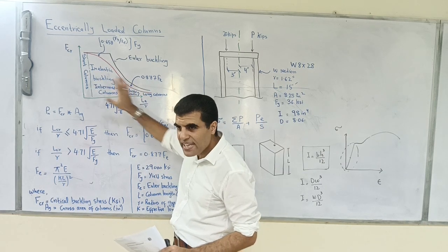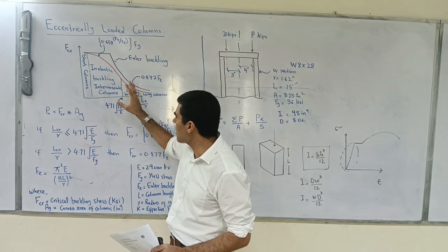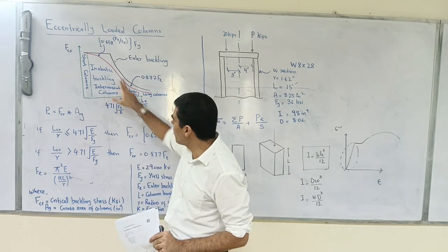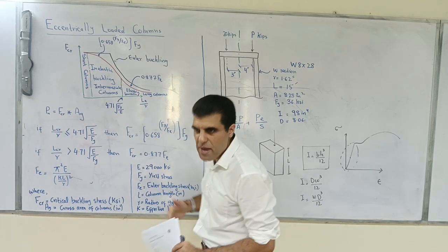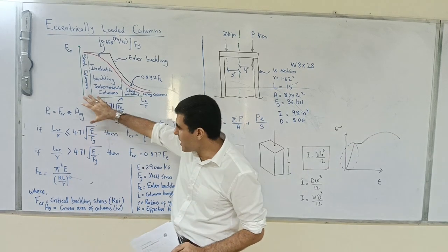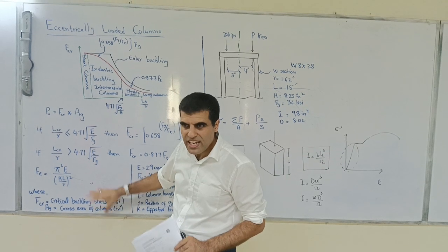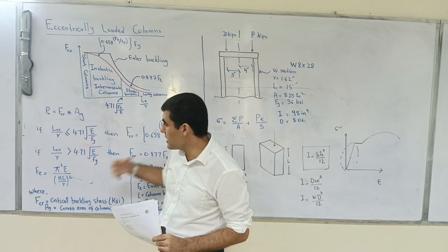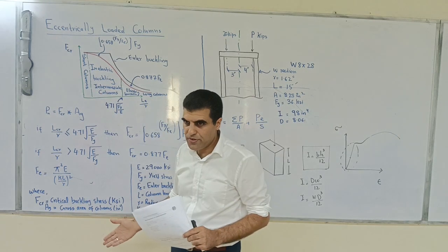Okay, so they divide the curve in the same way into long column, intermediate and short column, in 3 ranges. But they give you equations based on this red curve, which you can see is a parabolic curve. So this is from AISC. These are AISC equations which I have written for you. This is for steel structures. Normally for a steel member, if you want to find out the critical load in a column, you follow these equations.